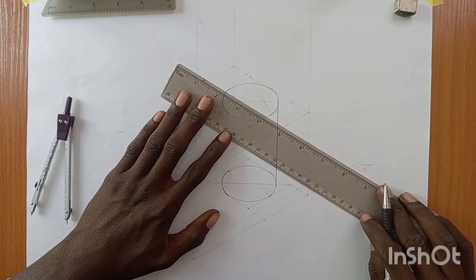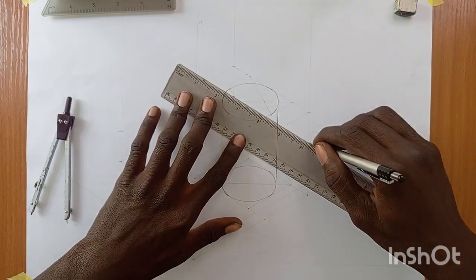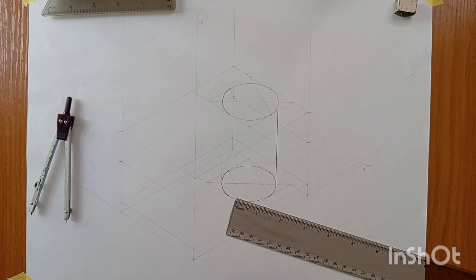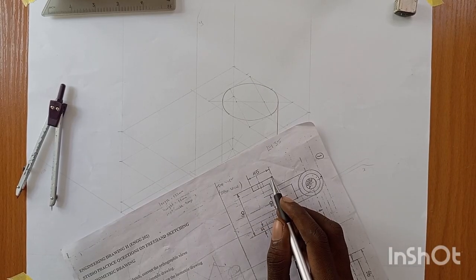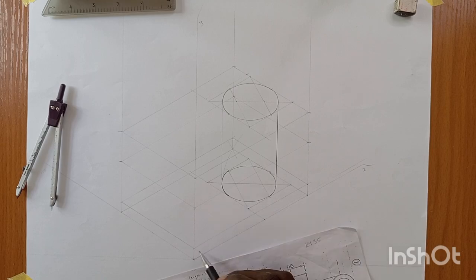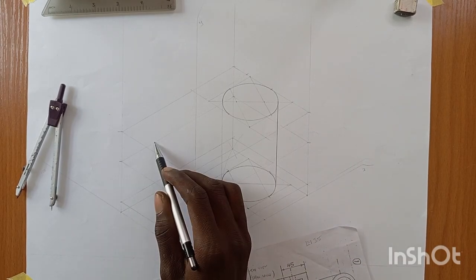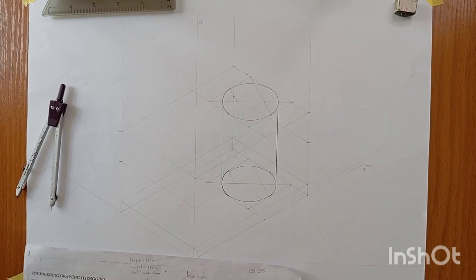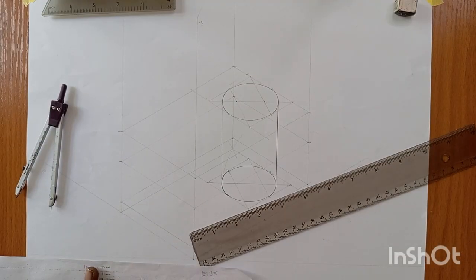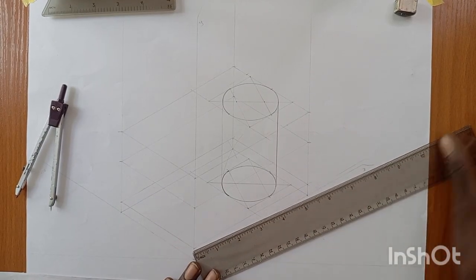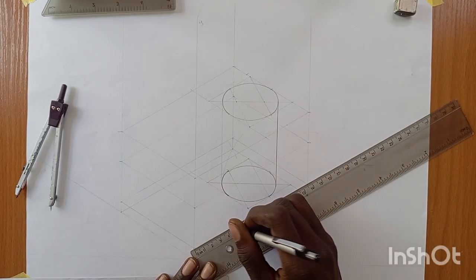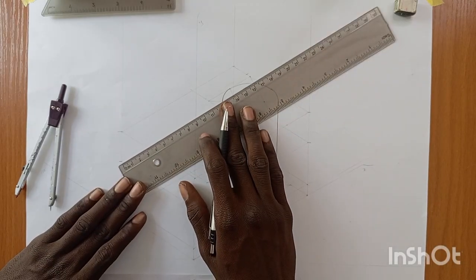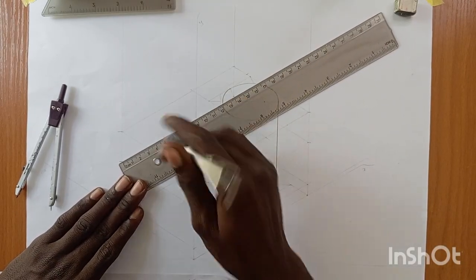As I've said earlier, whenever we cut any line in the vertical, on contour we are going to cut all the 4, as well as level, as well as the z-axis. Now, in here, as we can see, the length here, which is given as 45, we are going to draw it from here, 45. Also from here, 45. So now I'm going to measure 45 from here, that is from the base here, down the downside. So measure 45 from here. This is your 45. And then you can measure 45 here from the top or from the down, all the same. Anyone you do is correct.